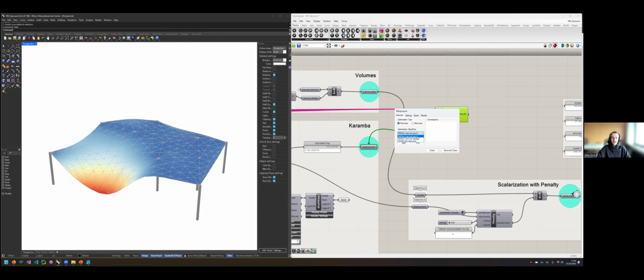So RBF opt might at one point just say, you know what, this is good enough, we're going to stop it here, whereas CMA-ES will just continue optimizing. So if you have thousands or tens of thousands of iterations, because your simulation is very fast, you can very well use CMA-ES.